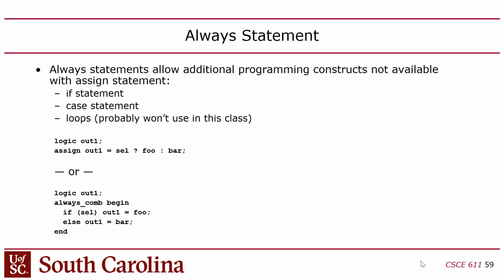And now here's where the syntax is a little different, because if you're in an always statement, you're allowed to use an if statement. You can't use it outside of an always statement. Why is that? I don't know. It's a very strange choice they made, right? But that's the rules of Verilog. Same thing applies to VHDL too, except in VHDL, instead of an always, they have something called a process, which is the equivalent mechanism in VHDL.